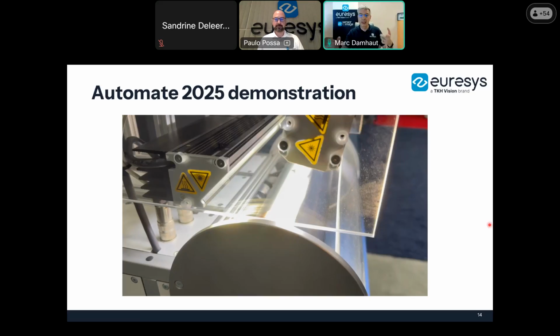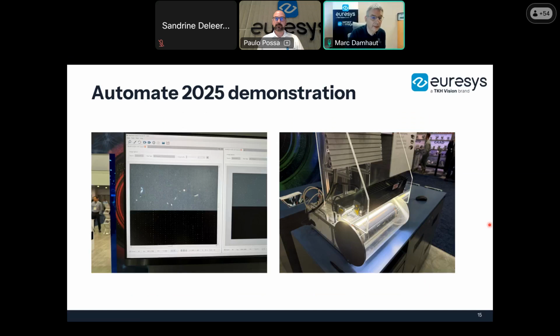So the camera acquires one line with the dark field lighting, and then one line with the bright field lighting, and so on. And this is the result. You see the setup again on the image on the right, and then you see the images that are acquired on the left. During the acquisition, it is the job of the Coaxlink card to separate these lines coming from the camera and to store them into two separate images in host memory.